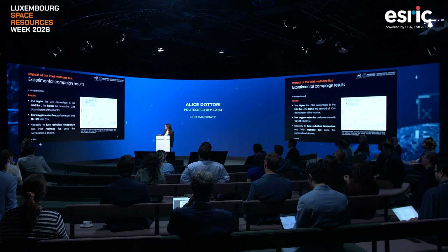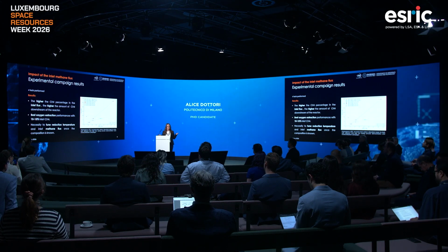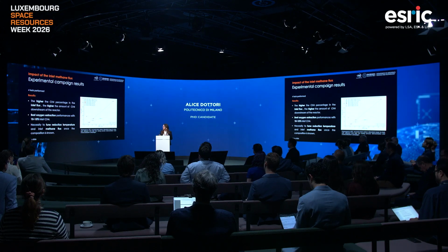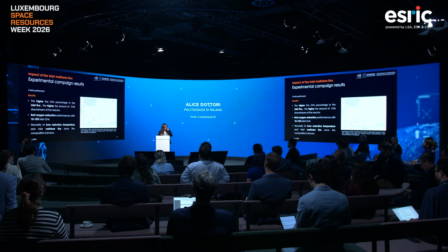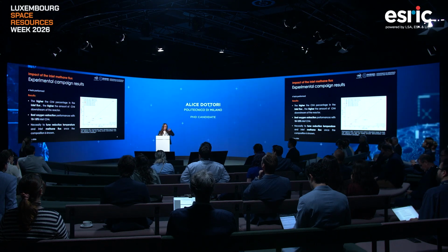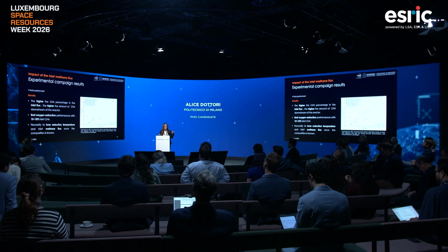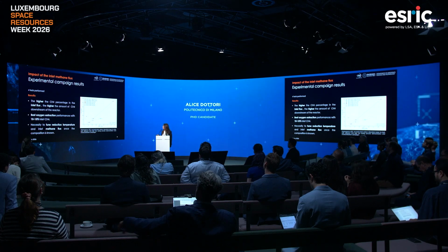That is our baseline. And we tried to decrease this percentage down to 5% and up to 20% to see if we can optimize the exploitation of methane, also because moving from 1 kilogram to 50 grams, we noticed a lot of methane downstream of the reaction. So meaning that this methane is just passing by and not interacting.